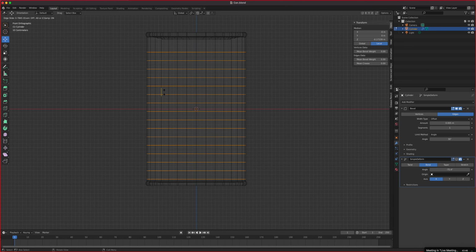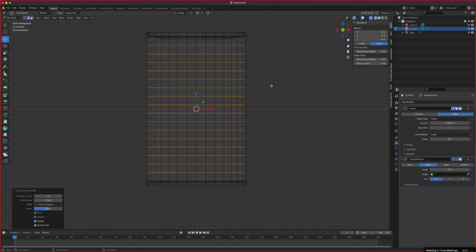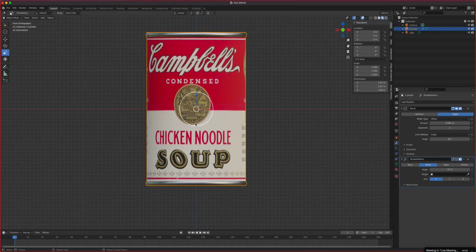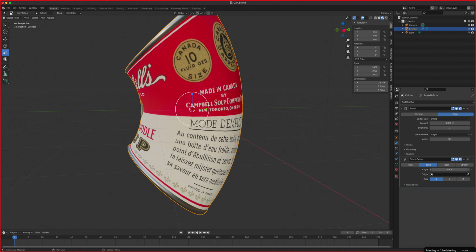Okay, and then it's going to ask you where you want to position those rings. Simply right click to cancel the movement, you want them centered, and if you kind of miss scroll your mouse, you can still change it here. So let's go with 15. 15 should be fine. Go here, go to object mode, and then turn on my bend. There it is. So now it's actually bending.